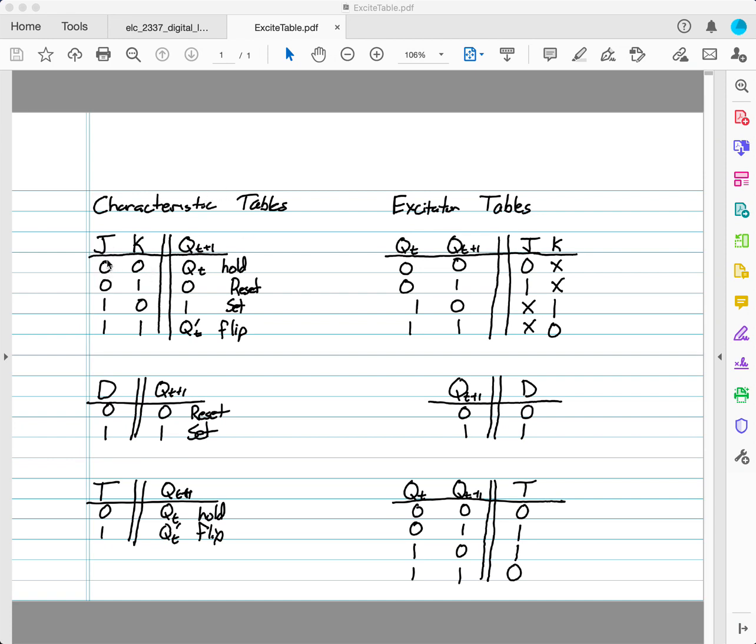Then you know what the inputs J and K are when you're walking through, because on the circuit, you can start on the left-hand side and just calculate the values through. You eventually hit the individual registers, so depending on the register type, if it's a JK, you would know what J and K are, and you want to know the next state, or you'd know what D is, or you'd know what the value T coming in is, and you want to know the next state, so you can fill out the table. So a characteristic table is used for analysis.